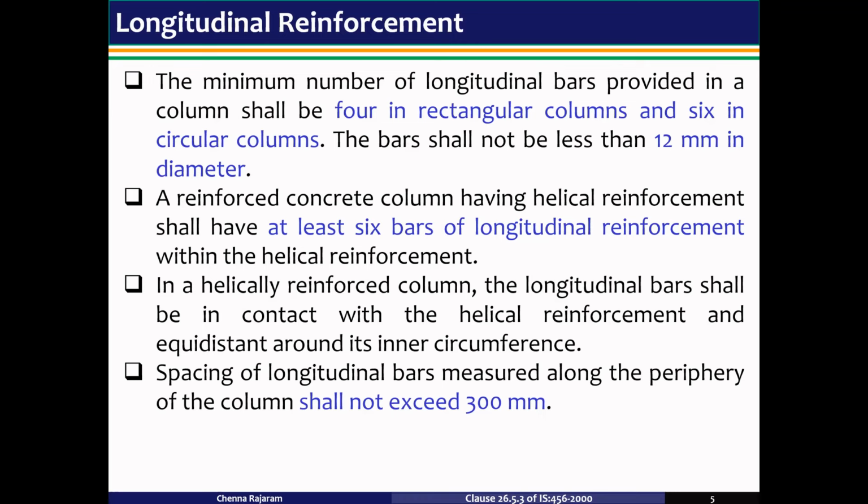For sections with several corners such as L, T, plus, at least one bar should be provided at each corner with proper transverse reinforcement.